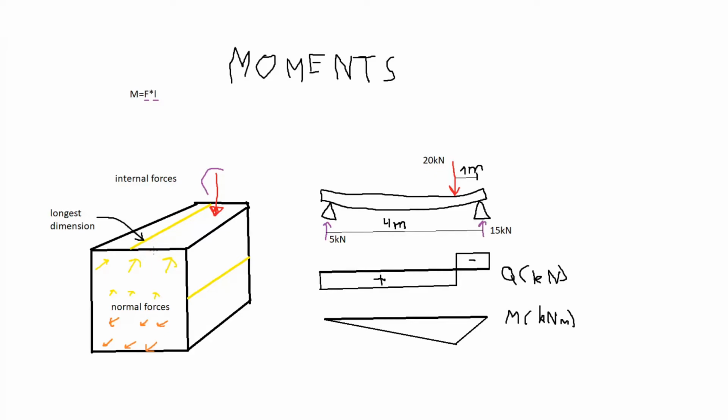When we want to find a moment right at this cut over here, we would multiply this distance over here times the magnitude of the red force. And notice, if we were to want to know the moment, for example at this point over here, let's mark it as point L, the moment would be much smaller because the distance is almost 2 times as small.